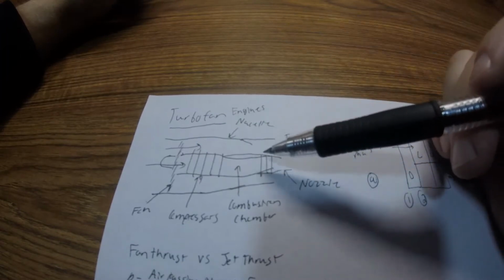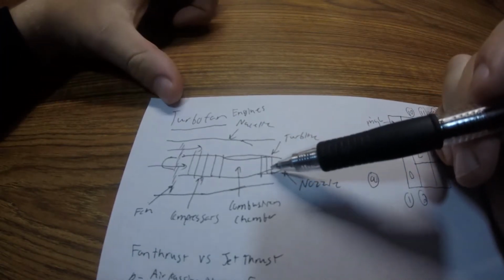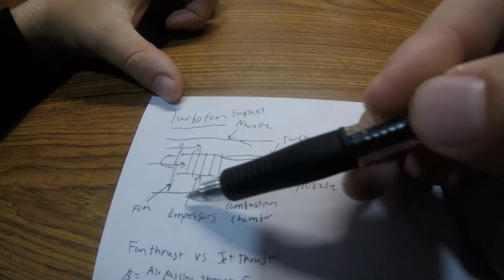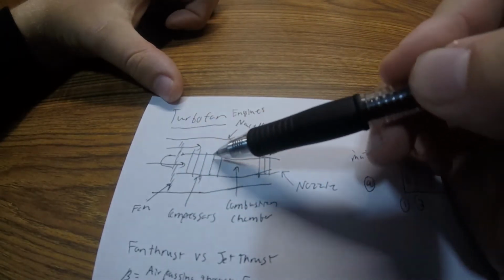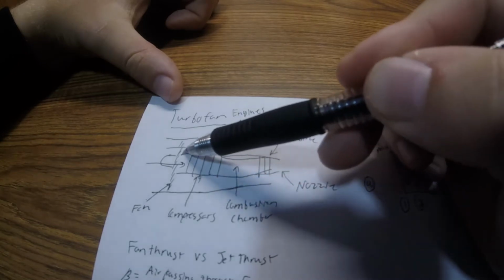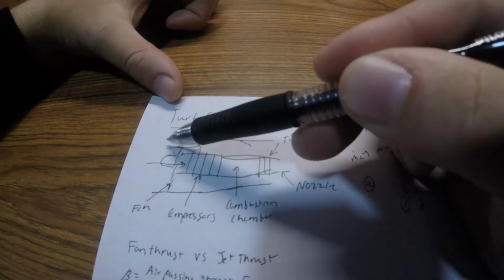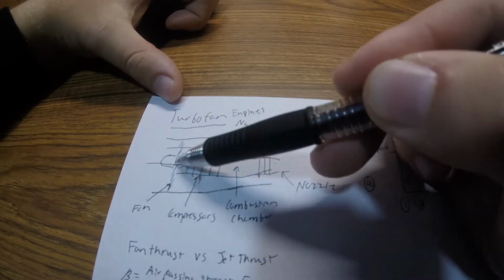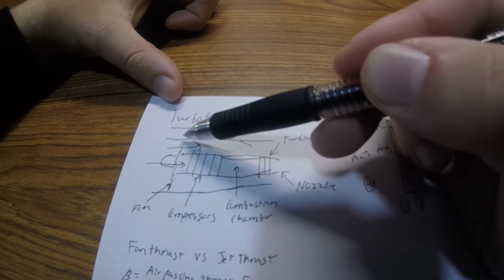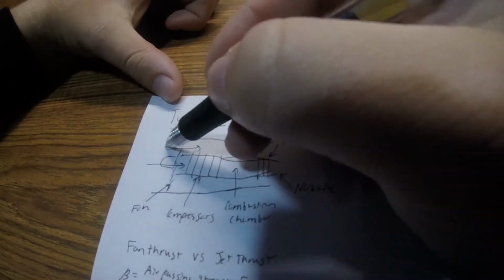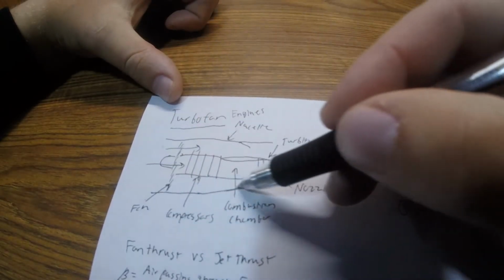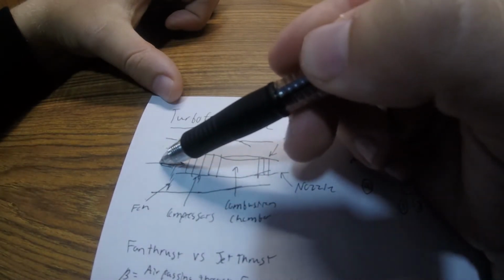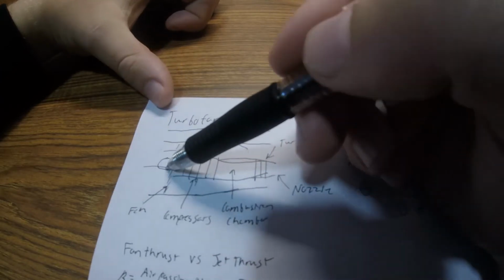Turbojet and turbofan engines are very similar in how they operate, but there's one key difference. In a turbofan, the casing of the engine is much larger than the core of the engine right here. This is the core. Then there's this casing, and a fan that covers the entire diameter of the larger outside of the engine. Air can pass through this section around the core of the engine, or the air can pass through the core.